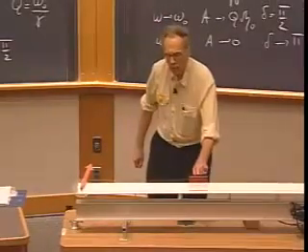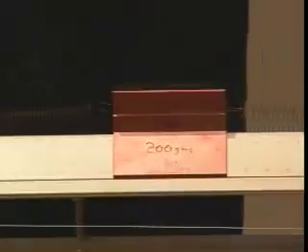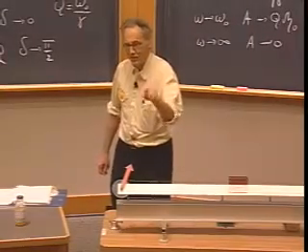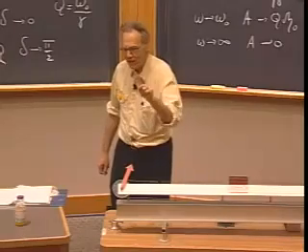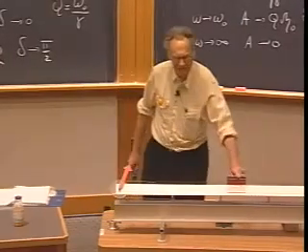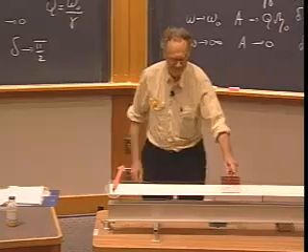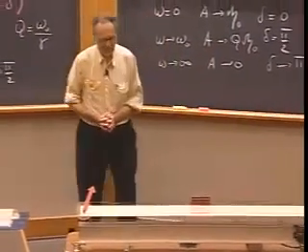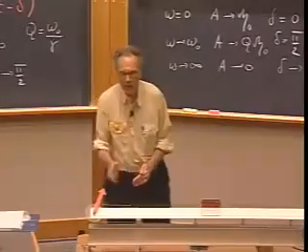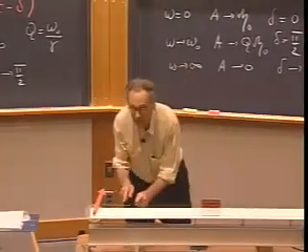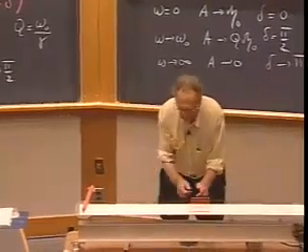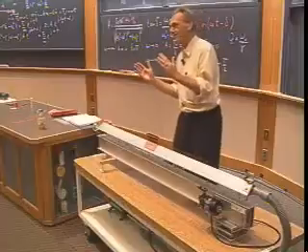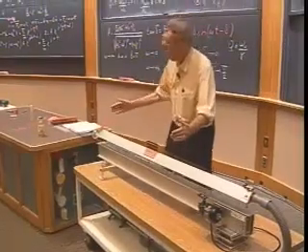What do you think the amplitude of this object will be at that very low frequency? Half of the amplitude of the... Very, very good. Not eta 0, but why is it half? Because we have two springs. So effectively the spring constant is twice that. Exactly. So if I go very slowly, you will see that this displacement here will be twice as high as this displacement. But what I really want to show you is they are in phase. This one will go to the right when this one goes to the right.